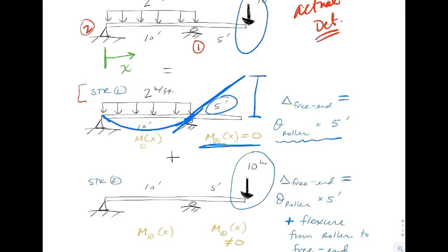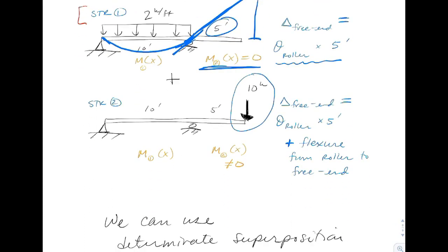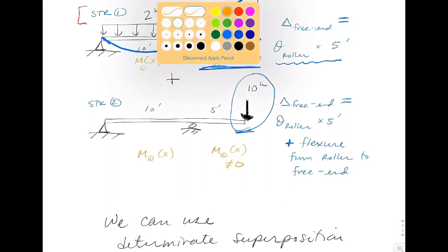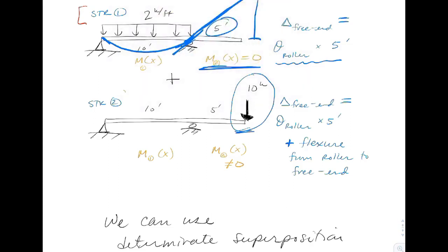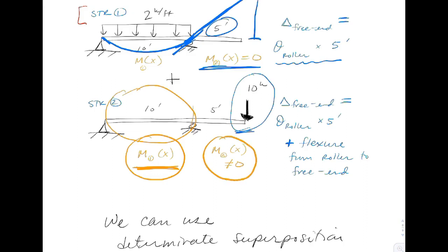We're going to have some tools. We're going to have a deflection table that's going to help us. Now, the one that's a little tougher to apply is the cantilever, the cantilevered overhang with the point load out here at the end. The thing to think about is that although we have no loads between the pin and the roller, we definitely have moment in there. We'll explore that a little bit more in class, but there is moment sitting in there. The moment is going to change on the other side of the roller because that roller applies a load to the structure.